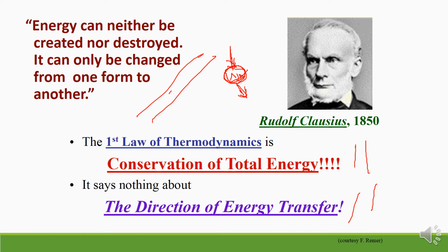So this is nothing but input minus output, that is equal to accumulation. At the same time we have to see what is the amount of energy generated in the system or absorbed by the system. That is very important. Different terms are considered here: the enthalpy term, the internal energy term, then heat capacity is very important again. Then enthalpy, heat absorbed, and work done by the system are again very important. That part is explained by the first law of thermodynamics.